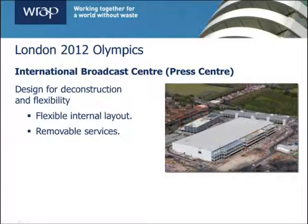The last of the 5 principles is design for deconstruction and flexibility. Again at the press centre, which was designed to be a permanent structure, the internal layout is flexible, and the steelwork has bolted rather than welded connections so that it can be easily adapted and ultimately deconstructed. The mechanical and electrical services, which are specifically related to the games, have been separated out so that they can be easily removed afterwards when they are no longer needed.